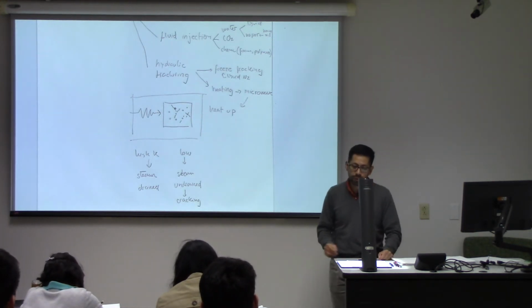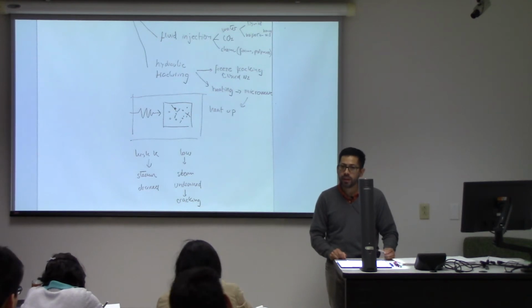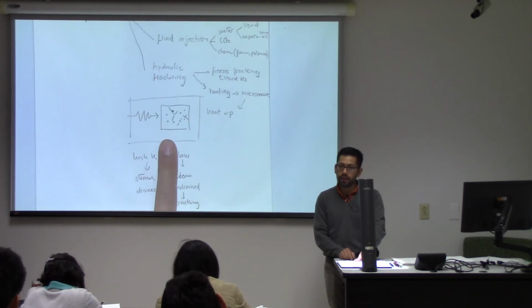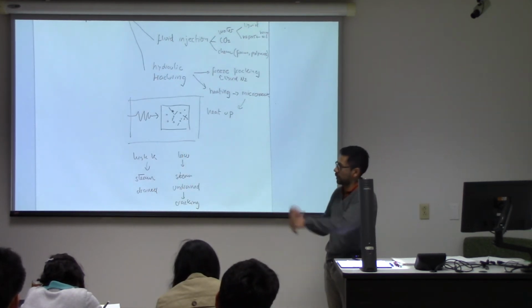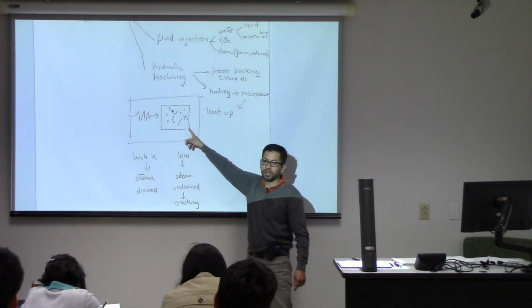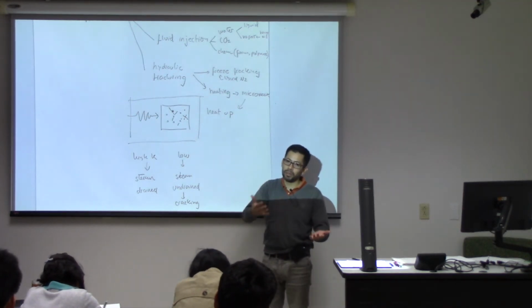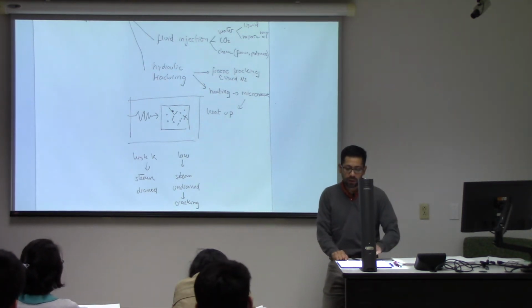So we know that those boundary conditions are not realistic in the subsurface. If you had this rock under confining stress with more rock to the sides, you could still create some of those fractures, but you would have to go into the mechanics of fluid-driven fractures in order to have something like that.